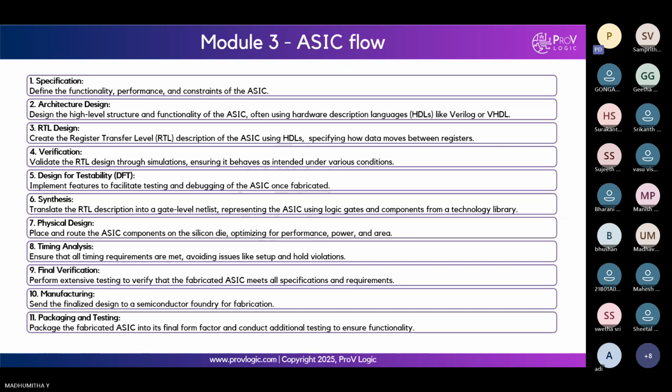Next is design for testability. There is one other separate set of engineers called DFT engineers. Again, DFT engineers are separate, we will not deal with them. DFT engineers will design some test patterns and they will give them to the physical design team. So we have to take those inputs and just implement them in our design. That part alone we have to work on. So designing the test patterns will be done by the DFT team. Taking those test patterns and implementing them on the IC will be done by the PD team, physical design team.